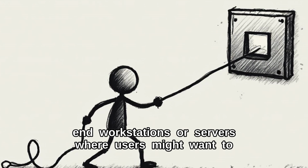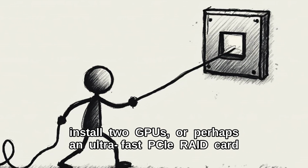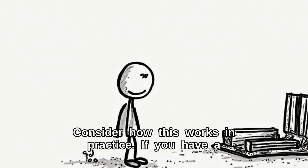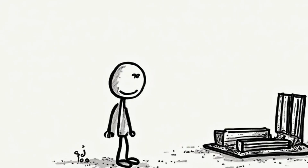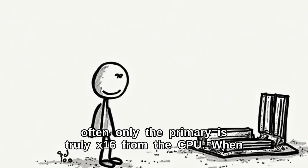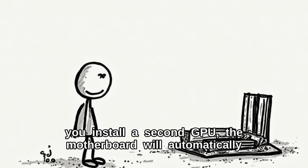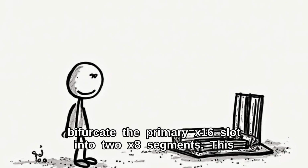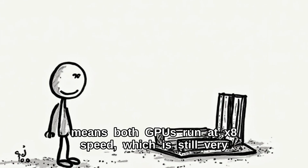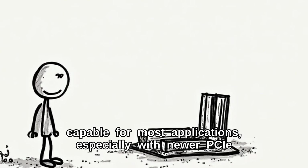This is often seen in high-end workstations or servers where users might want to install 2 GPUs, or perhaps an ultra-fast PCIe RAID card alongside a powerful graphics card, all drawing directly from the CPU. Consider how this works in practice. If you have a motherboard with a primary X16 slot and a secondary X16 slot, often only the primary is truly X16 from the CPU. When you install a second GPU, the motherboard will automatically bifurcate the primary X16 slot into 2 X8 segments. This means both GPUs run at X8 speed, which is still very capable for most applications, especially with newer PCIe generations.